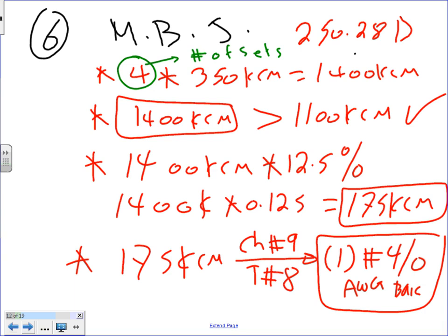Yes, sir? On that, I was just reading it. It says, not less than 12% of the area of the largest phase conductor. Yep. Would that be one phase instead of all 4? No, one phase if you're not parallel. If you read right underneath Table 250.66, it tells you if you're paralleling, you have to do the multiply by the 6. Did you find it?